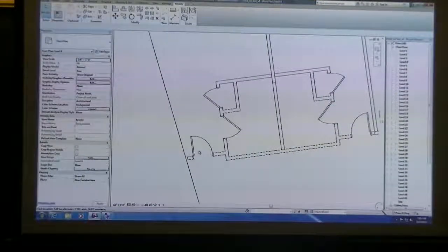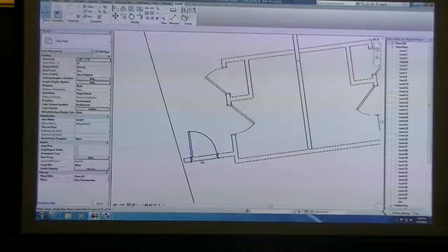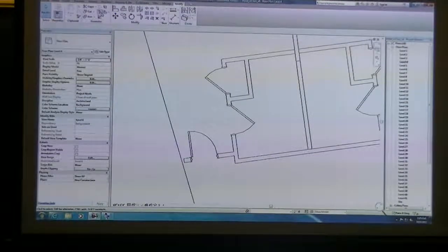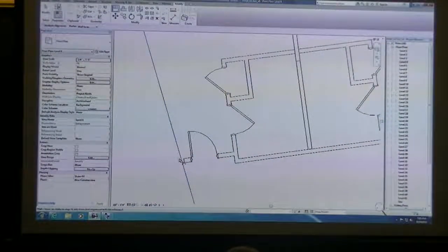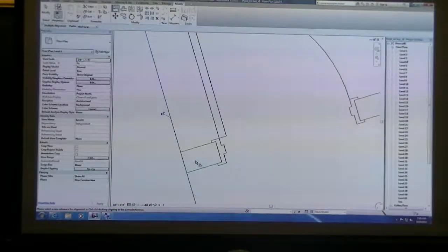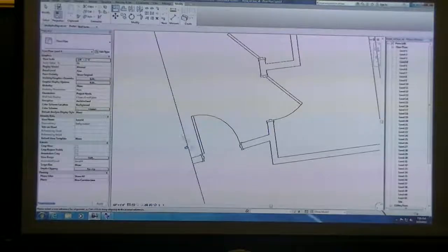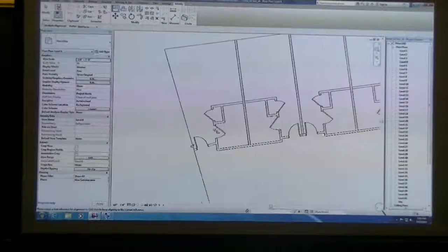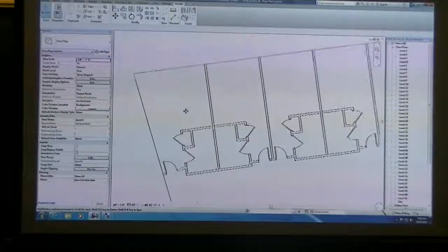And then I might decide that maybe this wall needs to be perpendicular to this exterior wall on this other face. This is where the align command still comes in. I told you we use this align command a lot. If you click on that, I'm going to click on this aligned wall, and then this portion of my wall to make it connect, and watch what happens. It aligned my wall to be exactly angled with whatever angle this turns out to be. So you can make these kinds of modifications as needed.